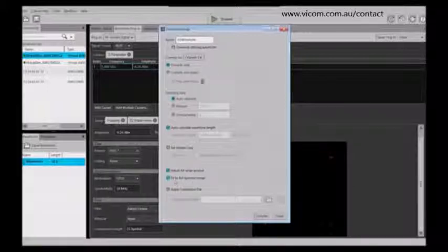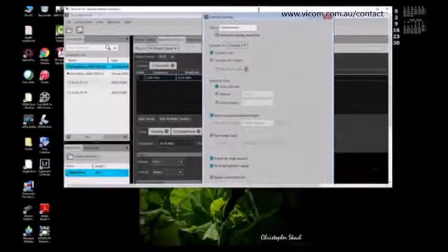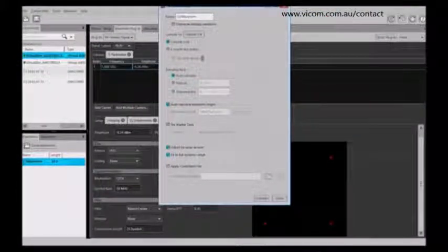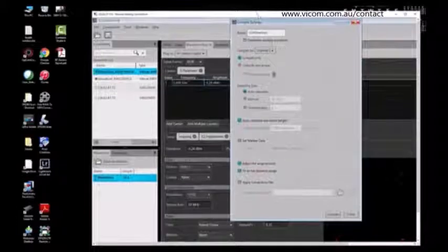We normally want to fit to the full dynamic range of the DAC, so most times you want to use the full DAC range. And this will affect your amplitude settings depending on the actual AWG that you're using and what your dynamic range is. So you have to take that into consideration. We also have the capability, when you compile a waveform, to use the correction file that you created using the pre-comp utility that I showed you earlier. So this gives you complete flexibility for using this correction file. So this is very useful.